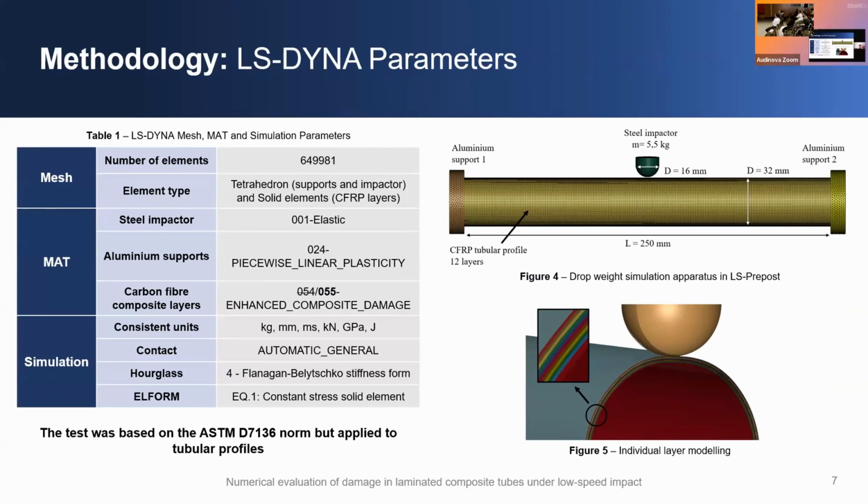Okay. And adhesion as well? Yes, it does, but like I said in the conclusion, it's not the best approach. I could have used, well, I've tested that there's a function called cohesive elements, or another MAT that accounts for that, but I had many problems due to my geometry and the fact that I'm using 12 individual layers. I had to create an interface between the layers and the software, or at least as of now, I do not have the knowledge to perform that.